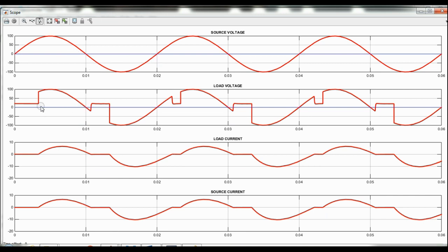So this is the RLE load. You start at this point. Here I am triggering T1. So this is the R effect. Here you will have the L effect, that is the negative waveform. As the current is not zero yet, you will have some reverse flow, not reverse flow, a voltage reversing effect. Then E: as the current is 0, T1 is off and V0 will be equal to E.